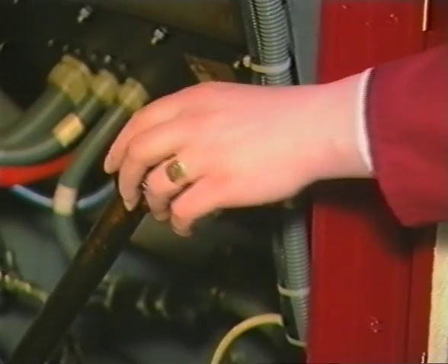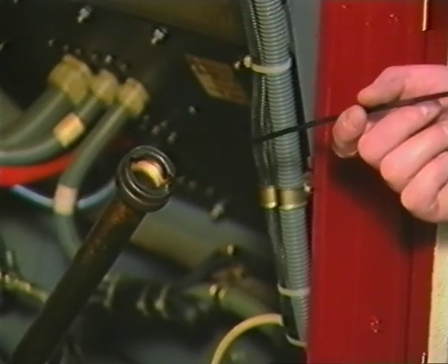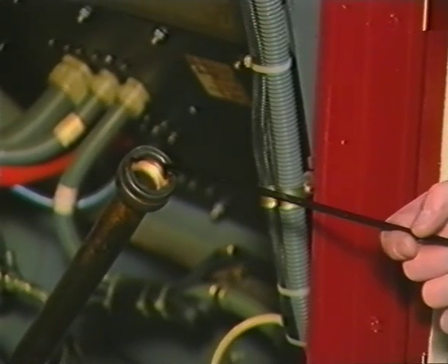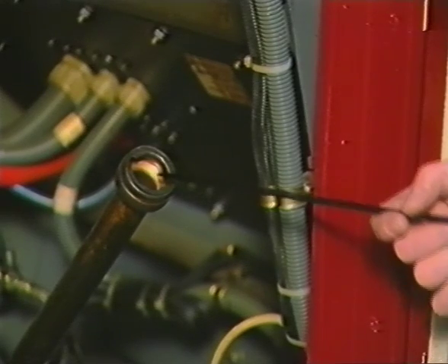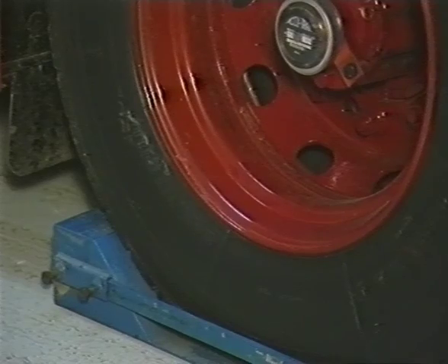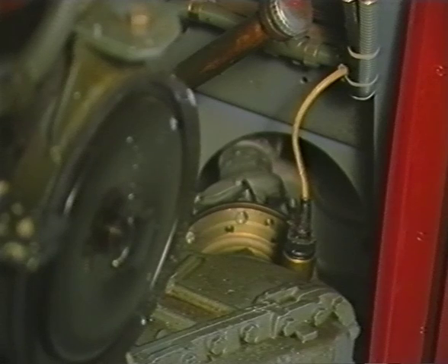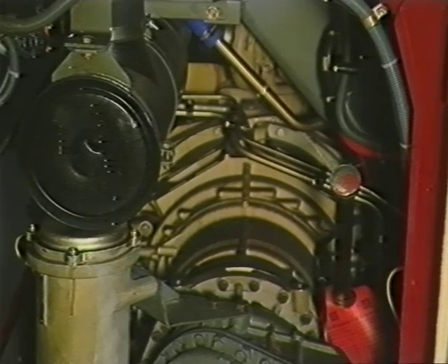This towing procedure should only be carried out providing the oil level is correct in the gearbox and no mechanical defect is suspected. Should any doubt exist, either the axle shafts or prop shaft must be removed. Failure to follow this recommendation will result in serious damage to the gearbox.